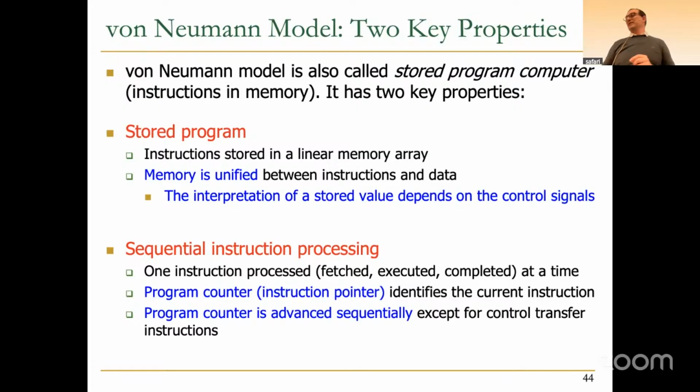Yes? Why is memory slower than the registers for temporary data? Because large is slow. If you have a large memory, let's say 2 to the 48 locations, imagine, based on what we have discussed in earlier lectures, how big of a decoder do you need? How big of a multiplexer do you need?